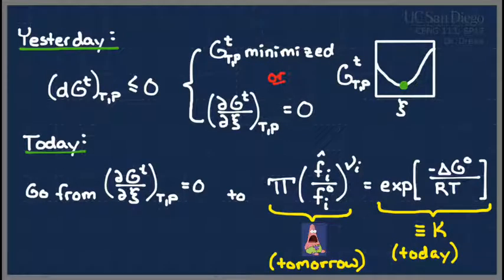I thought before we actually get to this derivation and how we do each of that, I'll just give you a brief review of why we want squiggle at all. Why are we going after squiggle? Why do we want these functions? Because at the end of the day, this function is going to be a function of things like temperature, pressure, moles of species that we have, and that's usually what we want coming out of a reactor. And we typically relate those moles of species through the extent of reaction. And so if we can arrange this form somehow that we can solve for an extent of reaction, it works like another piece of information about a reactor.